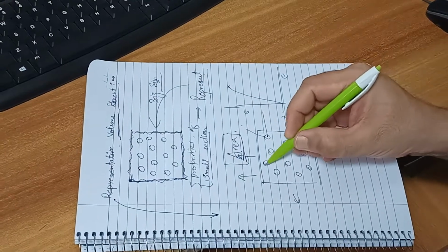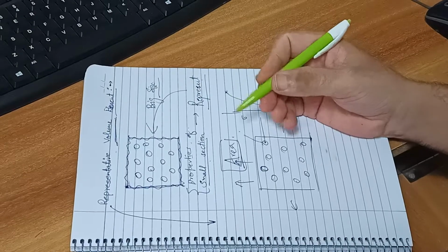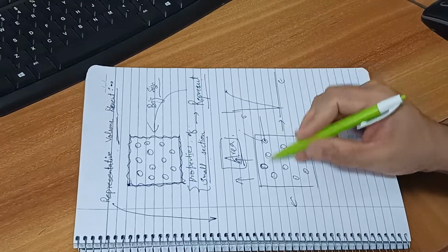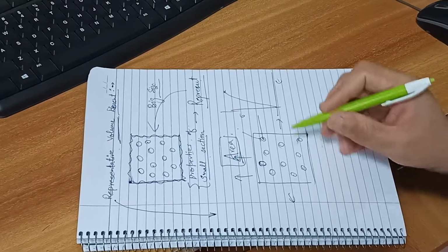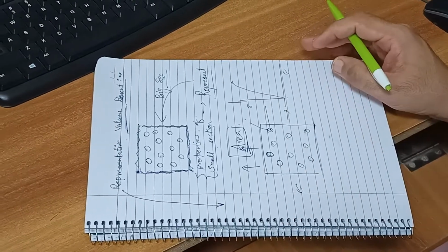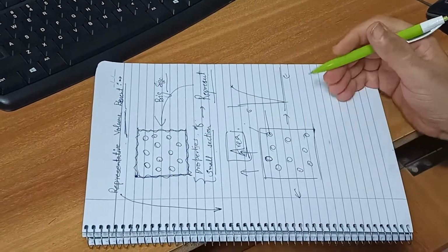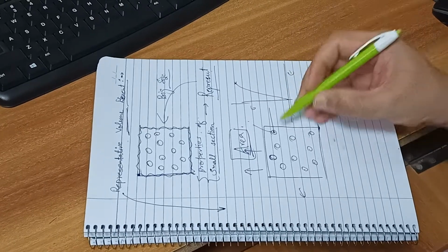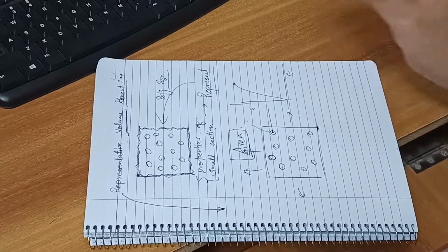If I load this point with, suppose, a greater strain rate or greater displacement, and this point is at a different condition of loading, then I cannot compare them. To have a fair comparison, I need uniform loading across all the points. Once you have a uniform boundary condition at all these points, then if you construct the stress strain curve of this fiber element, it will look something like this, as an example.